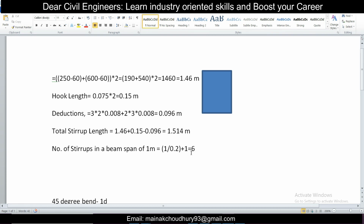So this is for 1 meter, and for any other span you can find out accordingly. Roughly for every single meter it will be around 6 bars, but you should not calculate like this. You should calculate depending on the total span. So the span, let's say, is 4 meters. It will be 4 by 0.2 plus 1. So this value will come to be 21. Like this, whatever number is coming, you can add 1, and the total stirrup length is 1.514.